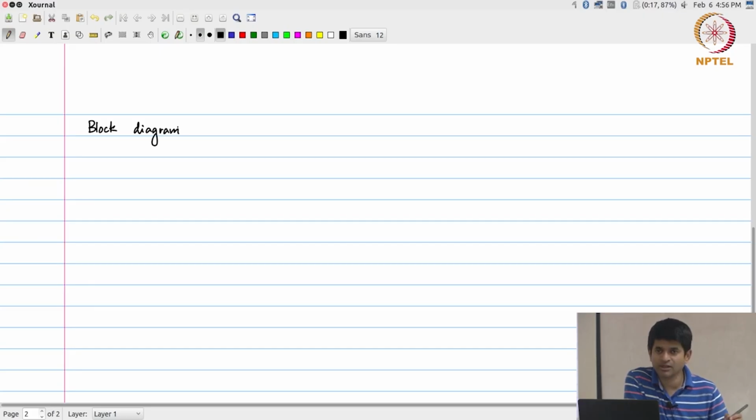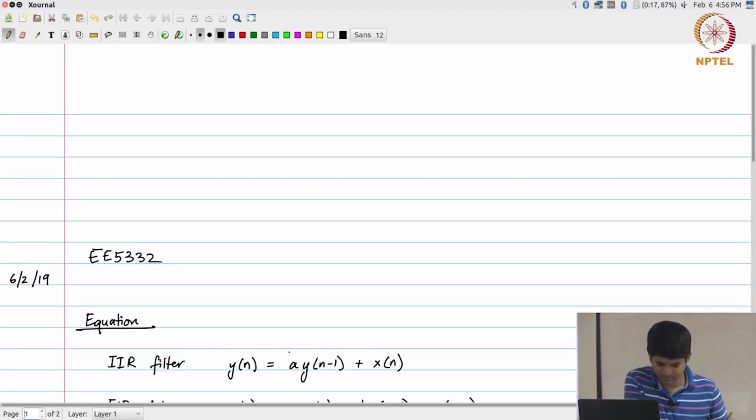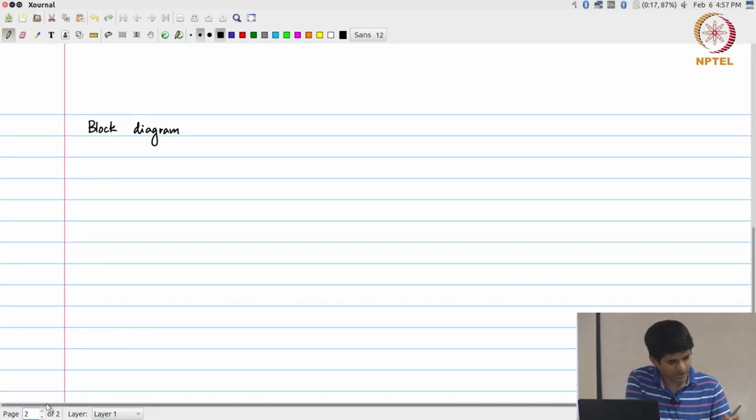An example of what the IIR filter would look like, right, we had the equation for it, which was y of n equals a times y of n minus 1 plus x of n, okay. The equation for that could be considered something like this. This wire, this arrow that I have drawn over here represents y of n. What I want is one sample delayed version of that, I use this rectangle to indicate that it is some kind of a register or some hardware that can basically result in a one sample delay.